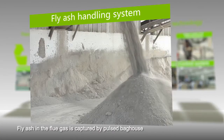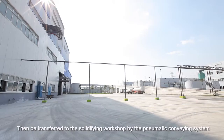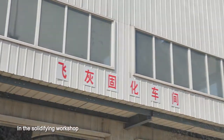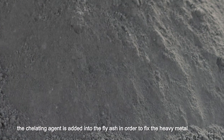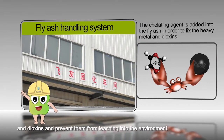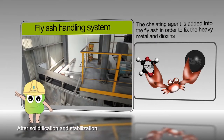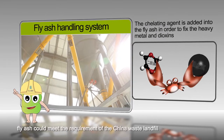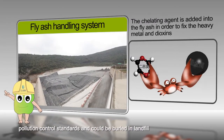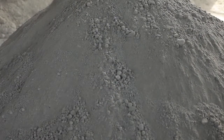Fly ash in the flue gas is captured by the pulsed baghouse, then transferred to the solidifying workshop by the pneumatic conveying system. In the solidifying workshop, the chelating agent is added into the fly ash in order to fix the heavy metal and dioxins and prevent them from leaking into the environment. After solidification and stabilization, fly ash could meet the requirement of the China Waste Landfill Pollution Control Standards and could be buried in landfill.